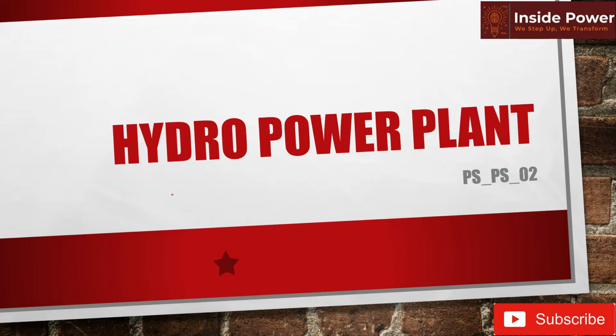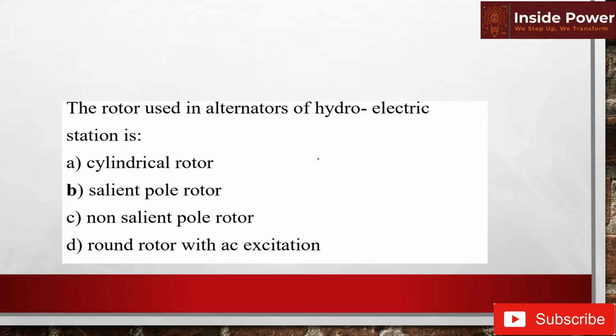The rotor used in the alternator of a hydroelectric station is: cylindrical rotor, salient pole rotor, non-salient pole rotor, or round rotor with AC excitation. Basically, cylindrical rotors are used for thermal power plants, whereas for a hydroelectric alternator we use a salient pole rotor. This is the answer for this question. Other options C and D are not valid for the alternator of a hydroelectric plant.